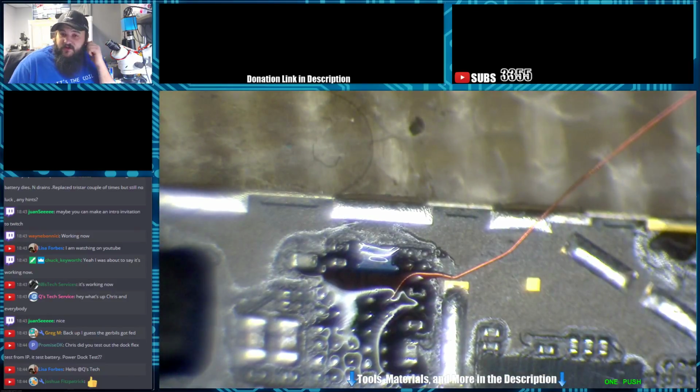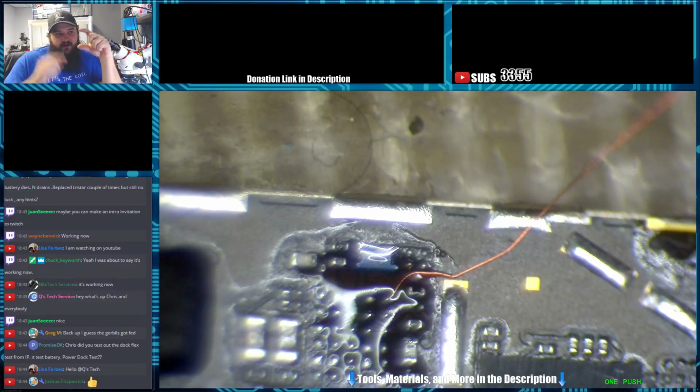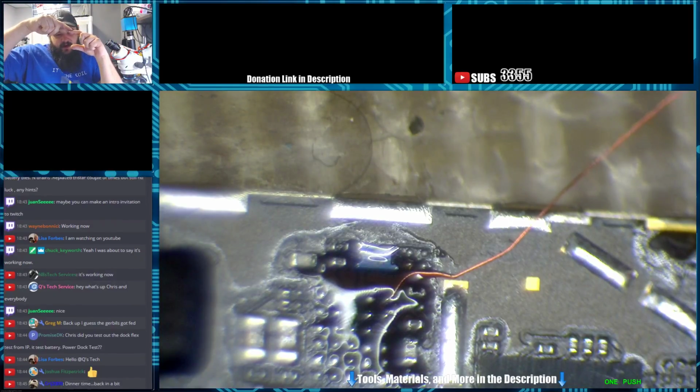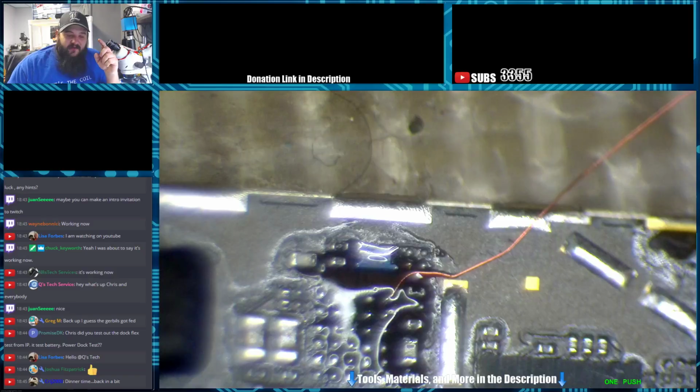So the way a voltage divider works is you have a power source. There's going to be a power source here at the top. We're going to do top down. So power source coming into a resistor, here goes to the output of the resistor. The output of this resistor will go to a signal line to an IC. The other side of that resistor also will go down to another resistor that's tied directly to ground. So whenever there's a voltage coming through the first resistor, the first and second resistor, their resistance is used to calculate a voltage that will be output between the two. That voltage is usually, if it's an even number, will be half.